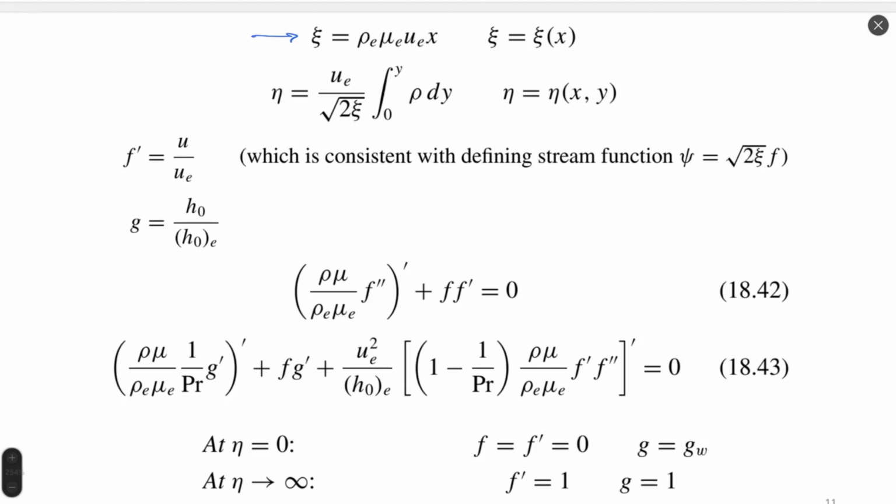And the second eta function will present to us a combination between X and Y direction, but mostly the Y direction. Because X is in a square root and Y is in a linear dimension, so it represents more the Y direction than the X direction, but it's the same as for the previous approach. For the Blasius solution, it is a combination between two dimensions.